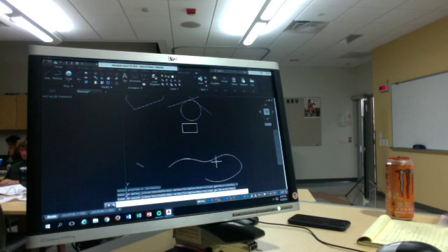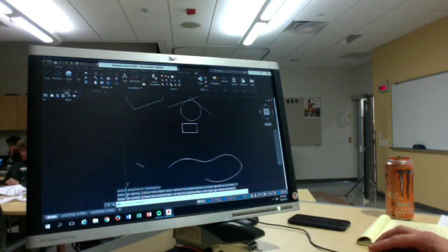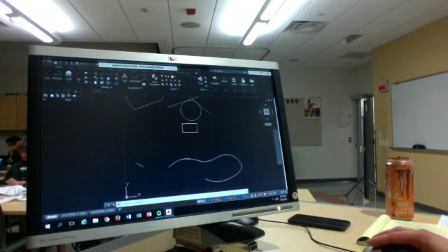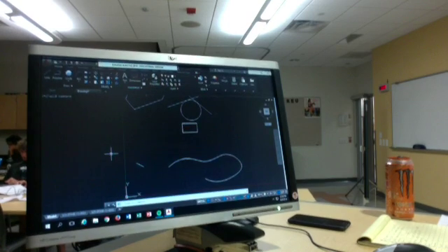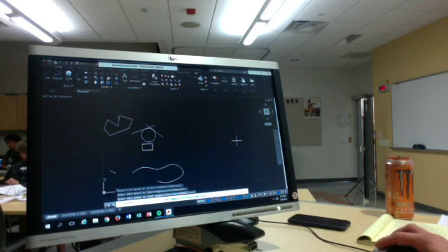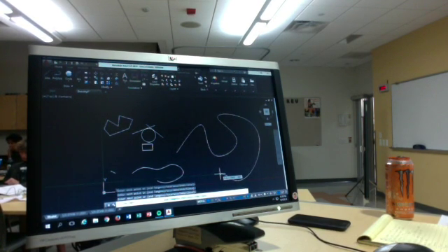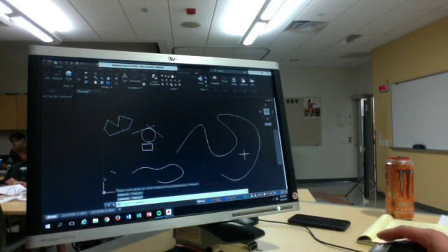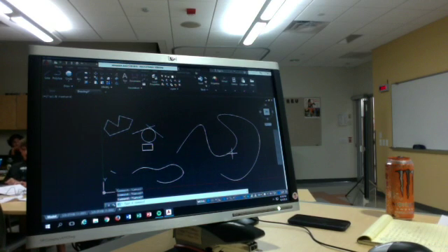You can also go right into making a spline. So you can either choose spline in your draw menu, or just type in spline. And you can draw a spline on all the points that you need. Now, you do have to hit enter a few times here. So the first time you hit enter, you can actually choose to modify it a little bit. Second time you hit enter, okay. Yeah, hitting enter once does exit out of it. I was thinking of another command. I'm sorry.